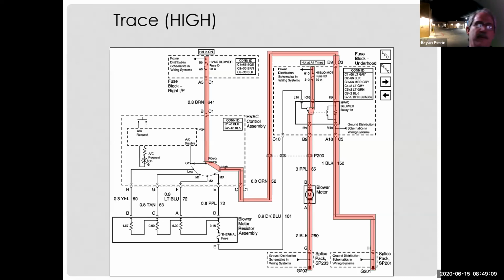And that's why, if I have a car that doesn't work right, the first thing I do is get the wiring schematic. Because I can't go test the vehicle without having the schematic, unless it's a circuit that I've repaired several times and I already have it memorized. But that's the first thing I need to get. And the thing that's funny is everyone wants to go test the car. No one wants to go and look up the information to test the car. And then they wonder why they spend 3 hours chasing their tail.